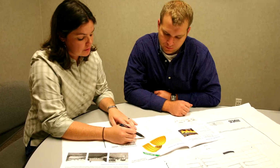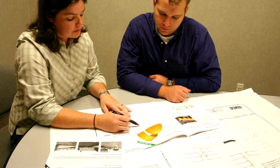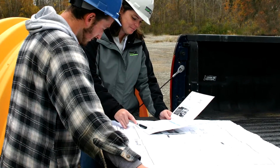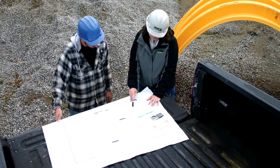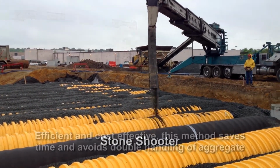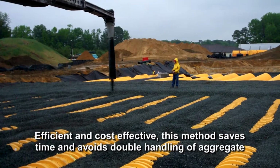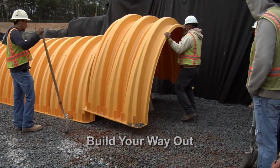The first step is to set up a pre-con meeting to discuss the required steps, establish a timeline, and determine an appropriate method for placement of embedment stone. Here are three commonly applied methods. With Method 1, a stone shooter located outside of the excavation evenly places embedment stone over the entire bed in a continuous manner. Method 2, the most commonly used method, is to lay one or more chambers at a time across the bed.